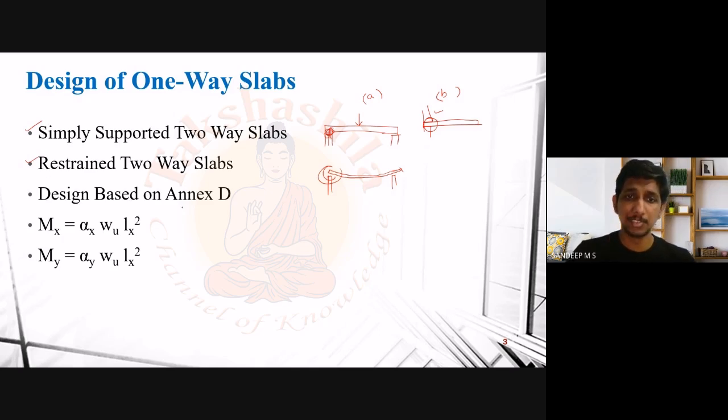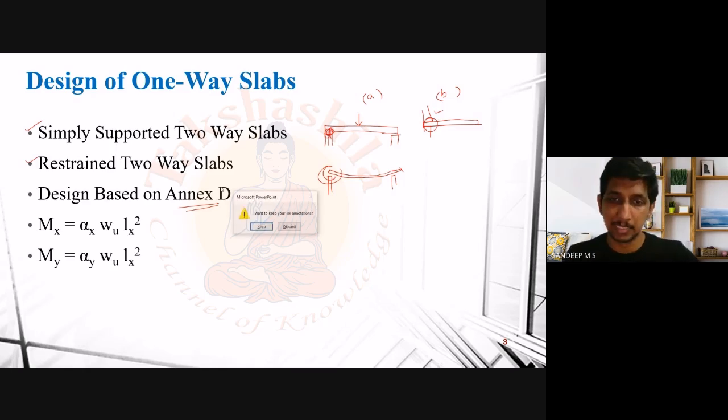And the design of two-way slab can be performed based on the procedure given in Annex D of your IS 456:2000. If you refer to your code towards the end, you have different annexes starting from A to I, I think E or F. Some annexes are there, and in that, Annex D corresponds to the procedure to be adopted when you design your two-way slab. Let's go to that annex and discuss the remaining things.